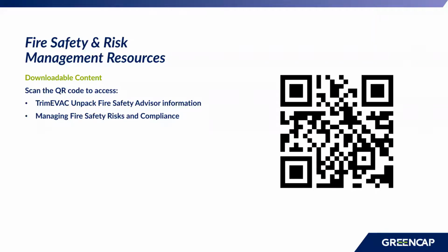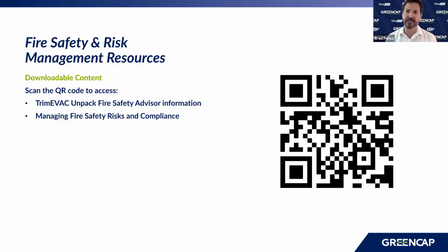Okay, so Natalie asked, do exit doors have to open towards the flow of traffic? I'll get that one. So it's important to distinguish between an exit door and a door in the path of travel to an exit. Sometimes what people see as being an exit door is in fact a door in the path of travel. And I guess if you think about what an exit door is, it's really a door that leads directly to the outside. So it's the door on the perimeter of the building, or it's a door into a fire isolated stair, so into a fire stair.